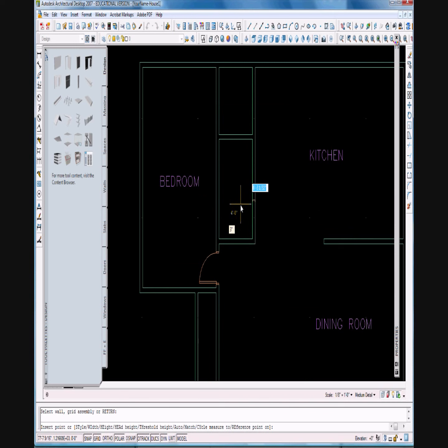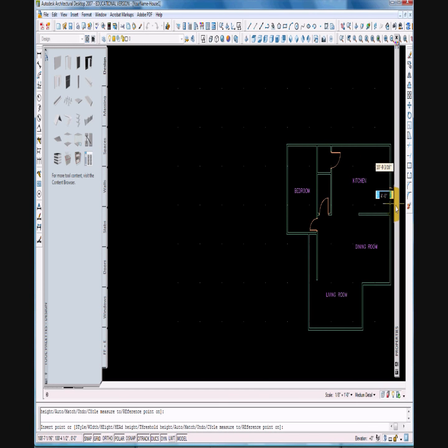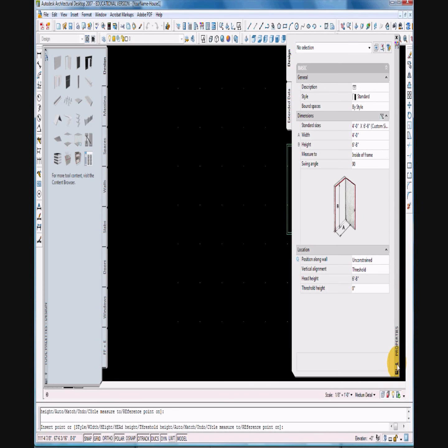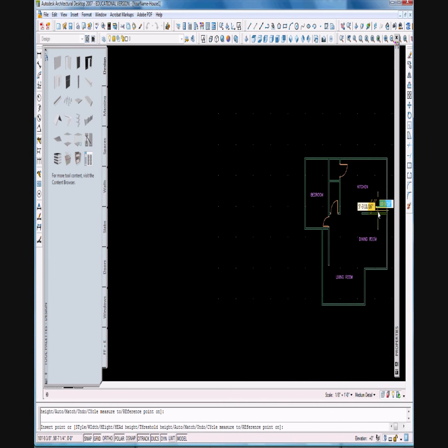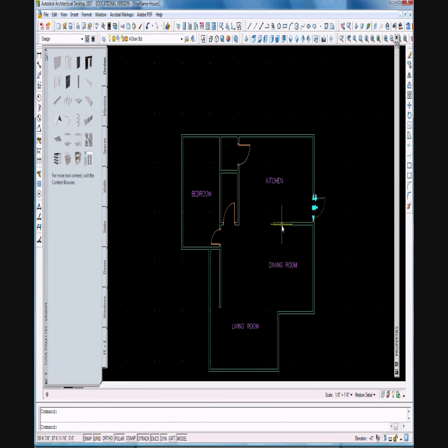So grab the door icon from the tool properties and add your doors. And I can zoom on top of an object and scroll with my mouse and zoom in and out. Another way of zooming in. And go ahead and release that door. And it doesn't have to be perfect at this point. But we do want to match the lesson.